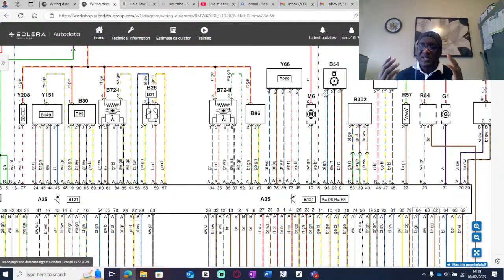But for the sake of clarity, because manufacturers sometimes do crazy things and move things around, I don't want you to burn your ECU, scorching it or frying it. James said, rule of thumb, number 2, the middle pin, is a signal wire. You can test all of them to be sure.